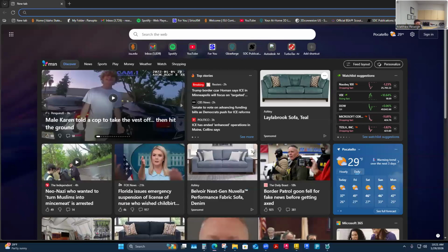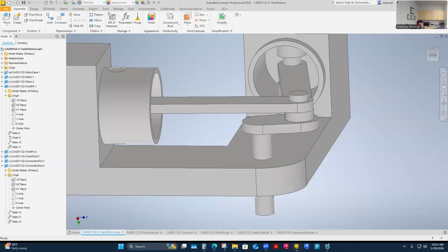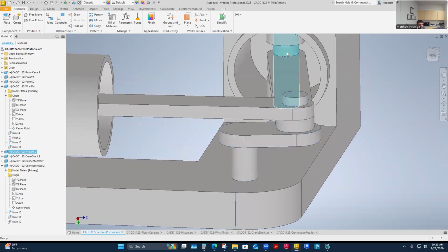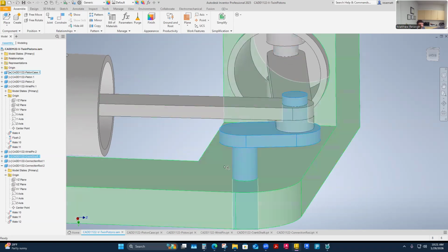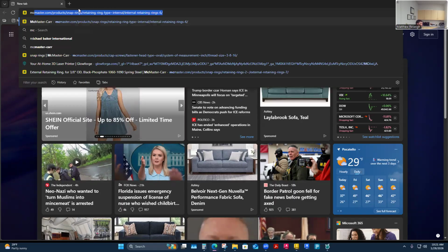And what you need to know though is some sizes associated with what you're working with, right? So if I go back to my screen real quick, these are 3/8 diameter shafts. The wrist pin is 3/8, 0.375. This little crankshaft pins, or all of its shafts are 3/8. So I'm looking for a keeper for 3/8. And so when I jumped over to McMaster-Carr, here we go.